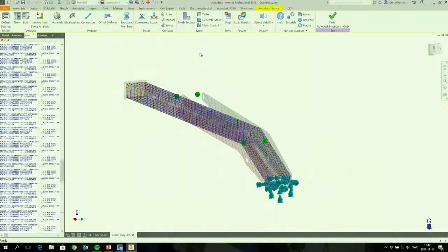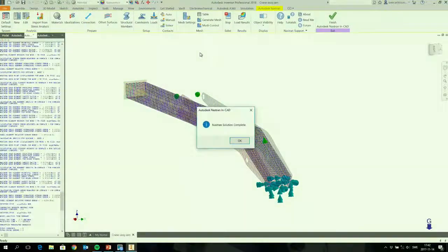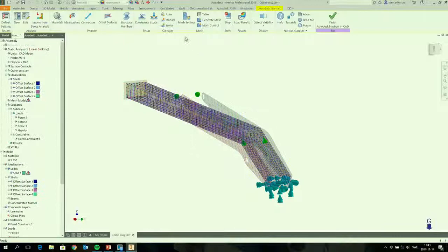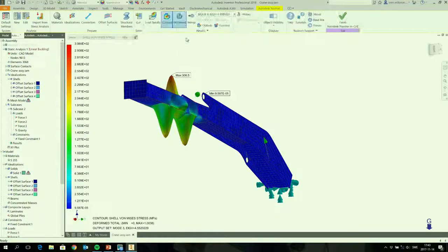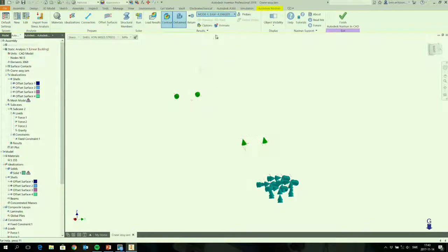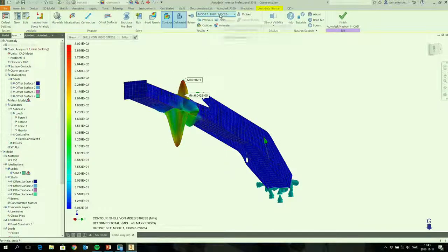So it's easy to work with modifications here to check what happens if we move now from 1.2 to 2. And what I get from this one is that we move from 0.82 to 3.75. So in a linear buckling analysis, we have a safety factor of 3.75.